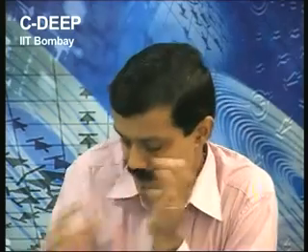For the sake of convenience, we divided the total zero vector time into two, and we applied 0, 0, 0 and 1, 1, 1. Okay, this is like this. See in this figure, assuming that we are in sector 1. Sector 1 is if theta is in between 0 to 60 degrees.